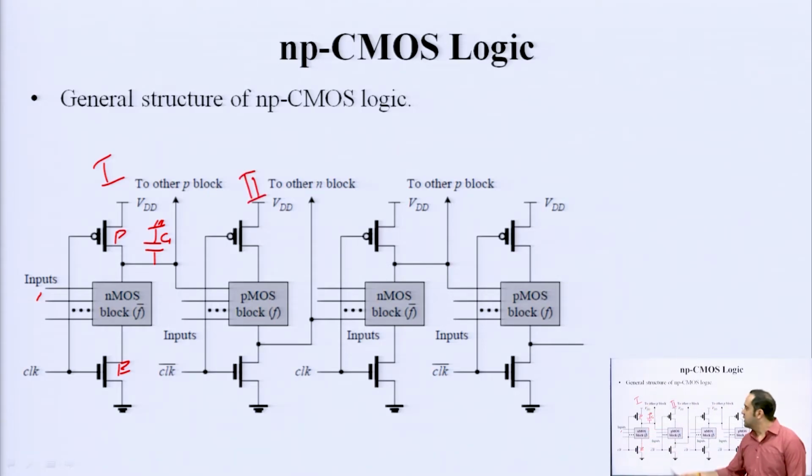The output of stage 1, there is no inverter in the middle, no other circuitry. It is directly being connected to one of the input of the pull up network which is consisting of PMOS transistors. So, here if it is visible, it is written F bar here, which means it is implementing inverting logic. There is an F here which means it is implementing non-inverting logic.